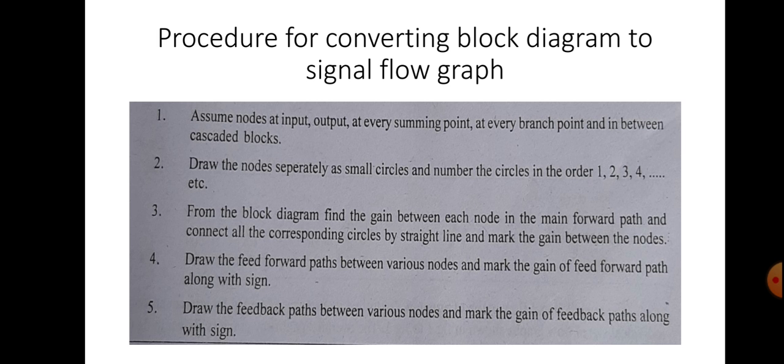Sometimes you are asked to draw the signal flow graph without a block diagram being given, then you have to derive the differential equation and convert it into Laplace transform form, and then identify input and output variables, and you can draw the signal flow graph, and you can finally combine all the signal flow graphs to get the signal flow graph for the entire system. That is the procedure.